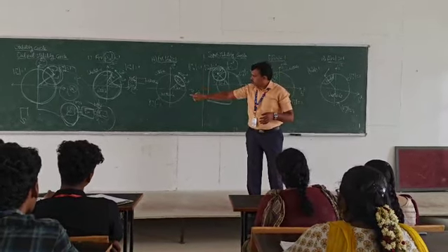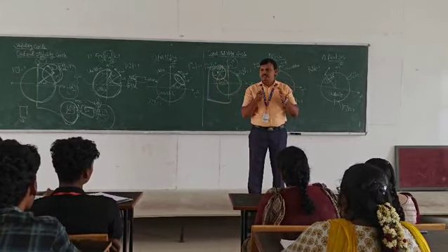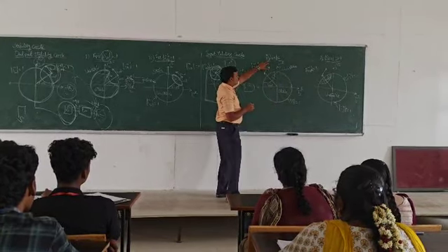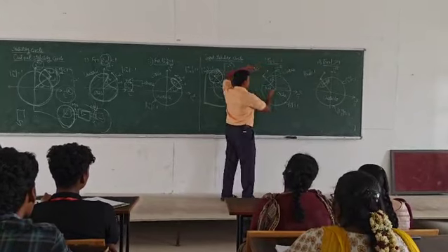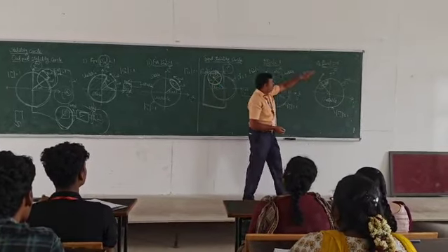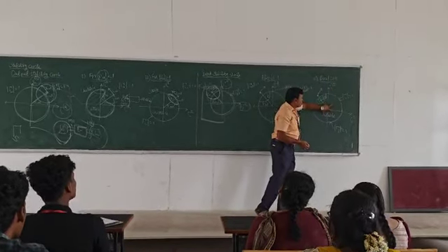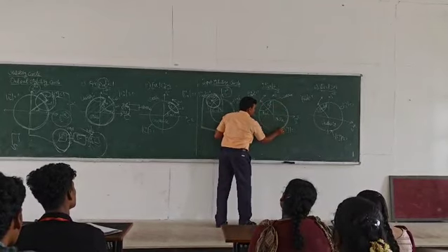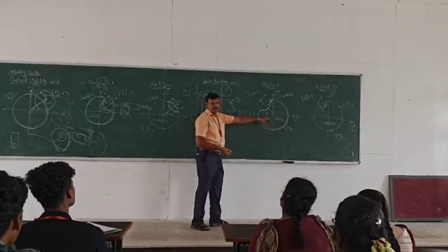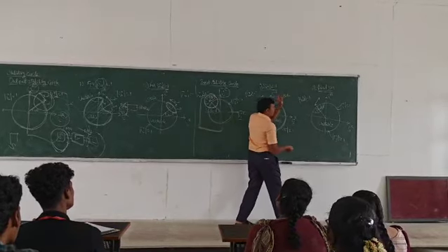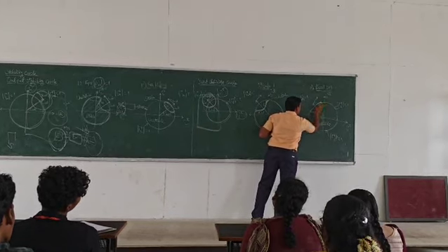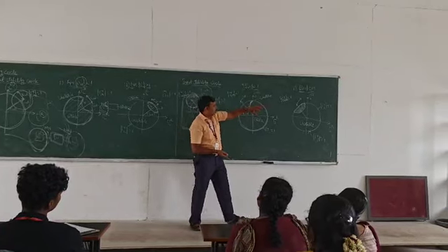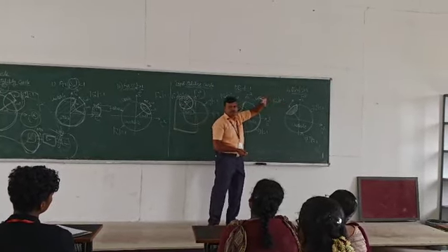First we focused on S11 for the output stability circle, and then for the input stability circle we focus only on port 2, that is S22. If the modulus of S22 is less than 1, we draw this circle. In the other condition, if the modulus of S22 is greater than 1, we draw this similar circle. When it is less than 1, the major circle is the stable region of our amplifier. When it is greater than 1, only the smaller circle is where the amplifier is stable.